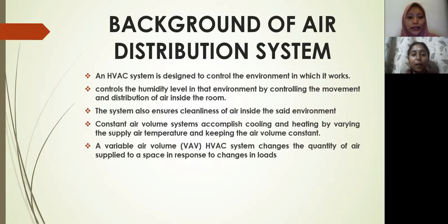CAV systems accomplish cooling and heating by varying the supply air temperature and keeping the air volume constant. VAV HVAC systems change the quantity of air supplied to a space in response to changes in loads.